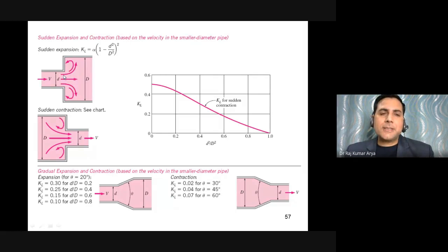In this case also, the fluid will go this side, and now there would be a circulation of the fluid in this corner and in this particular corner, and these two wakes would be formed, and these would be added to your losses. In the orifice type, you have seen the orifice is this type of connection, sudden expansion and sudden contraction both, and there your discharge coefficient for the orifice is 0.61, only because you have this type of flow pattern on the exit side here.